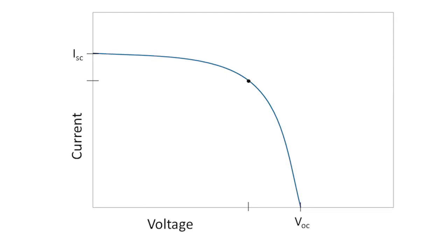But the VOC and the ISC are two extremes for voltage and current, and these are typically placed on a graph with voltage on the x-axis and current on the y-axis, and that is known as an IV curve. By increasing the load on the cell through increasing resistance, a cell will move from the ISC point to the VOC point, generating this curve. Adding resistance is the only way power can be extracted from the cell. In reality, this is the role of the battery or the inverter.